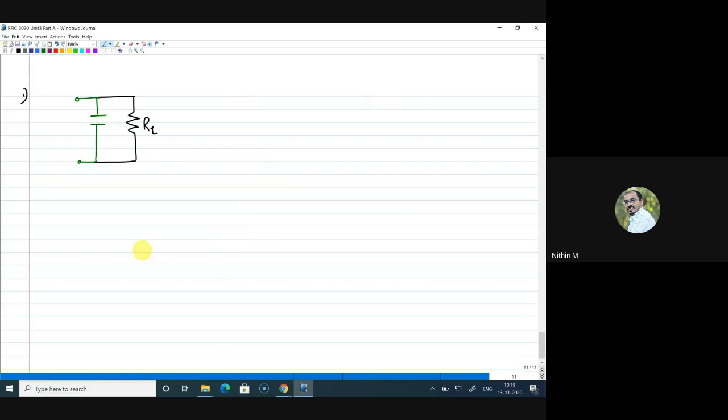Can you tell me what kind of transformation this will lead to? There is a resistance RL, and if I keep a capacitance in parallel to that, and I look at the resistance from here, which is a series component, it will be a downward transformation. Yes, that is true. Now our requirement is to convert a real impedance, a resistance, to a resistance only. But since I have added a reactive component, I should cancel the reactive component finally, right? So I'm adding an inductance here.